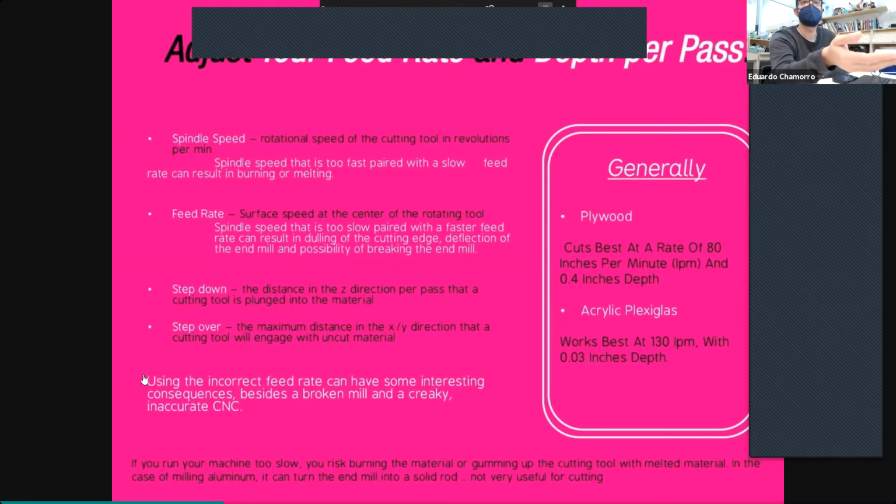Yes, but the machine starts screaming. It cuts hard, and things get messed up really fast. Basically you have no time to react. If you cut at 5,000 millimeters per minute and you hear a weird sound, you have about 2 seconds to touch the emergency button and stop. At 15,000, basically you don't have the time. The mill just slaps. There's no time of reaction.